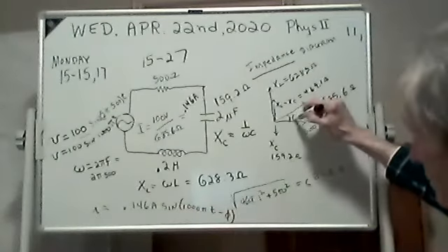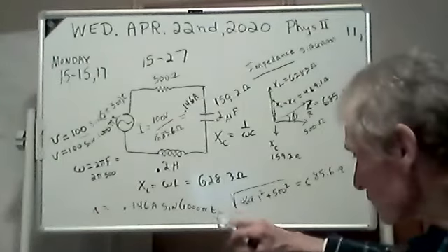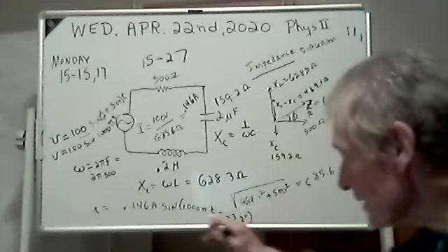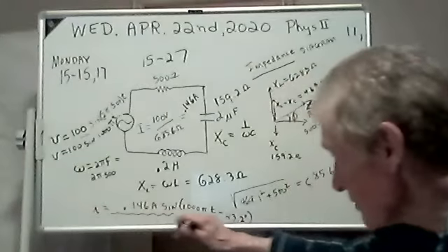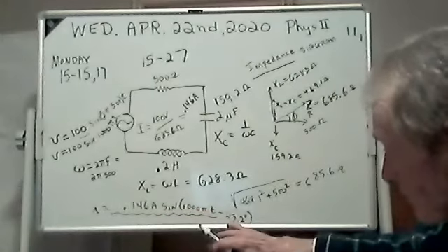See this angle right here? It's called a phase angle. We could get that phase angle. There's several ways to get it. You could go 500 over 685.6 and take the arc cosine. It's 43.2 degrees. We think this is the current. It's a sinusoidal current, and we have the angular velocity. We even have the phase angle.